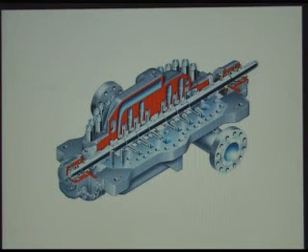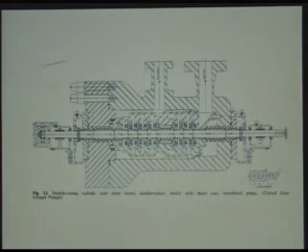which is then converted to static pressure, and it continues to rise as it passes from impeller to impeller to impeller. This one's horizontally split. This is a barrel pump for very high pressures. Same thing, the hydrodynamic section is a bundle that sits inside the pump.